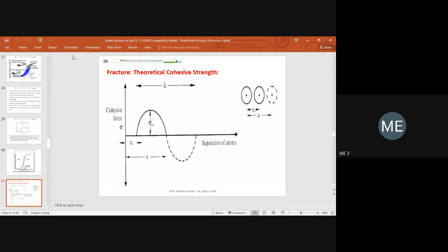Once glass is fractured, the overall surface area will increase. Imagine you have a chalk piece; if you pull it, it breaks into two pieces and generates two more new surfaces. The overall surface area will increase. To increase the overall fractured surface area, when we pulled or bent the chalk piece, we already spent some amount of energy. That is everything you are talking about in terms of the macroscopic level.